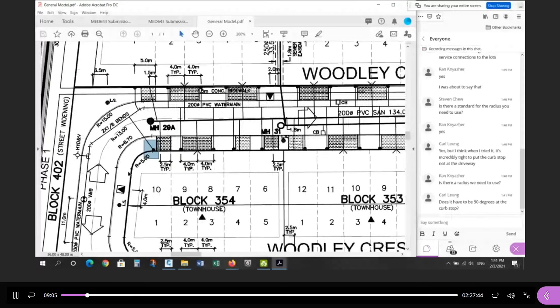Again, review what's in the existing subdivision, and there's a lot of examples of some of the stuff you're dealing with. Right? And the reason I believe this was the connection is because if they went straight across, they'd bump into that sanitary manhole. So they decided to go off to the side. Okay, again at 90 degrees to the pipe, but this doesn't have to be at 90.